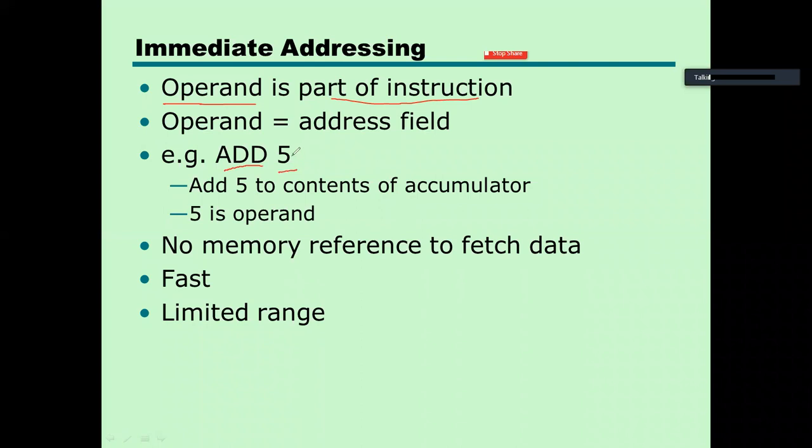Now, whenever we are performing any arithmetical and logical instructions, the result will always be saved into the accumulator register. It is also known as A, where your information or the addition will be saved. So for example, if there is data in the accumulator as 05 and we are writing ADD 05, then both the numbers will be added and the result will be 10 in hexadecimal.